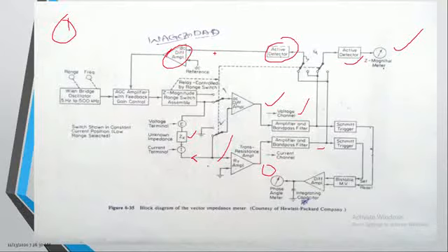And whatever the voltage we are getting from here, this voltage is compared with the DC reference voltage. If there is a change, we are taking the differential amplifier. Differential amplifier means which will compare these two signals and give the error signal. If there is a difference between the input signal we measured and the reference signal, then an output voltage is generated. This output voltage is taking the responsibility to adjust the frequency as well as the gain of this particular element.